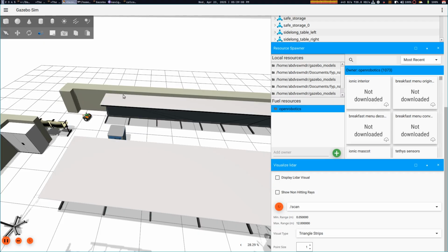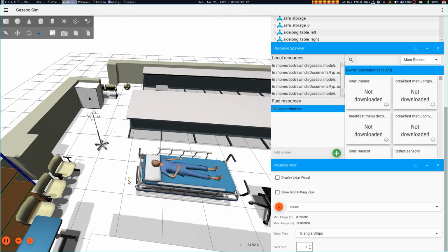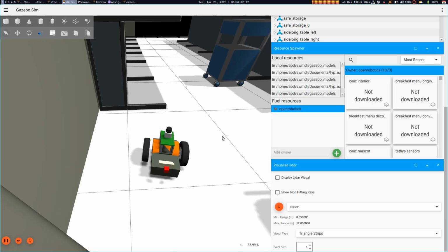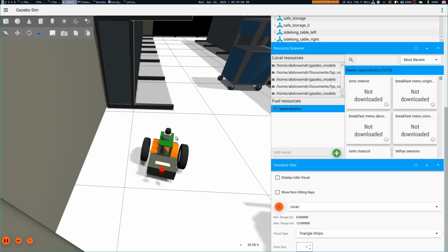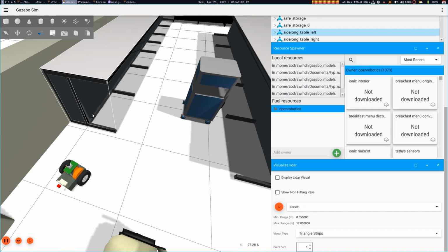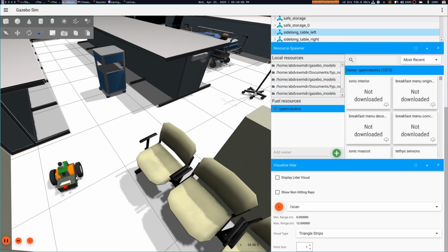And the other downside is the speed of the robot. It's slow, and that's because we're only using one LiDAR. Some people use two LiDARs, especially for the AGVs in the industry. Their precision is much higher, so they use one LiDAR here and the other one on the back, so that they can achieve 360 degrees here and here. So one LiDAR is responsible only for one side, so that's why it's much faster. And they also use cameras as well, so they use visual SLAM and they sensor fuse it with the two LiDARs.